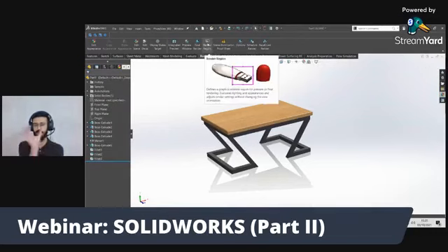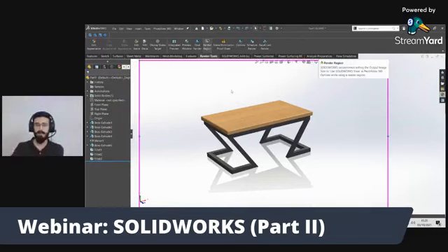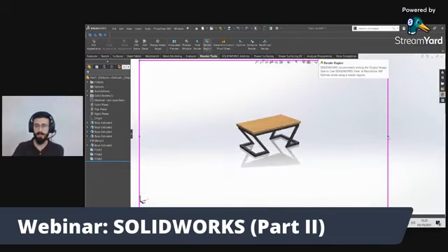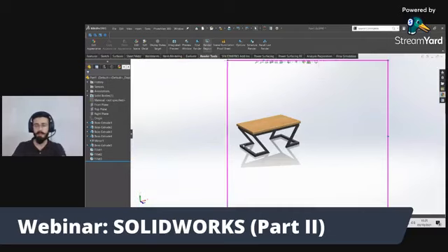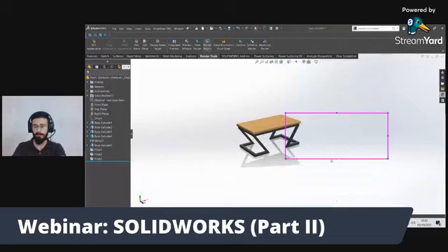And if you want to render just a little bit part, here is the render region. When I entered into the render engine, this much part is being rendered. So if I just want to render this leg of my table, I will just reduce my render region to the leg, like this, and only my leg will be rendered.